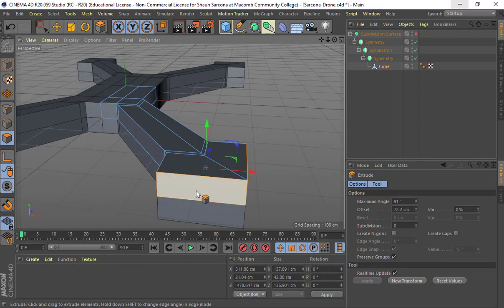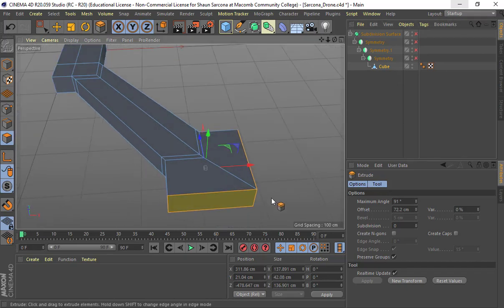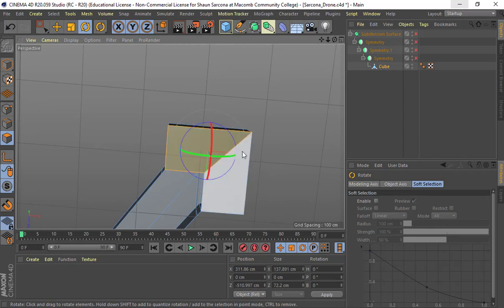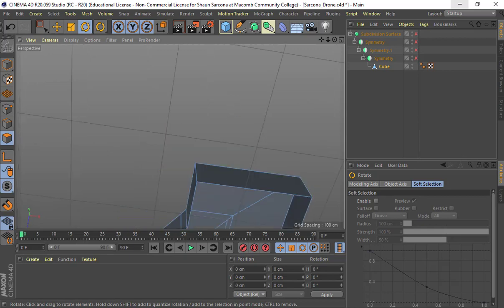Now, what do you think is underneath these faces here? If I turn all this off, what do you think I'm going to see when I flip this over? More faces, right? Every time we extrude, we'll get faces, so we have to make sure we're aware of that. You always delete those faces. Wherever they're connecting side by side, we have to delete those faces. Okay?